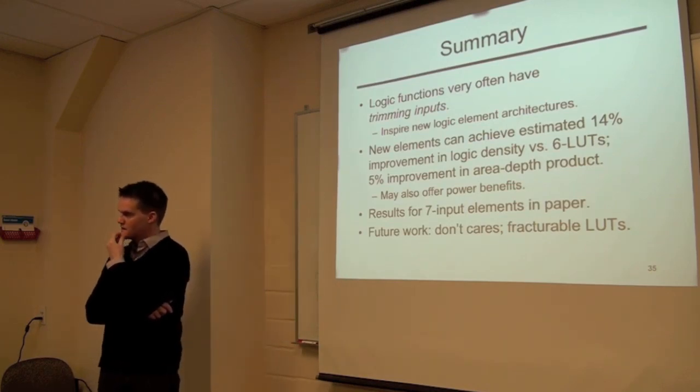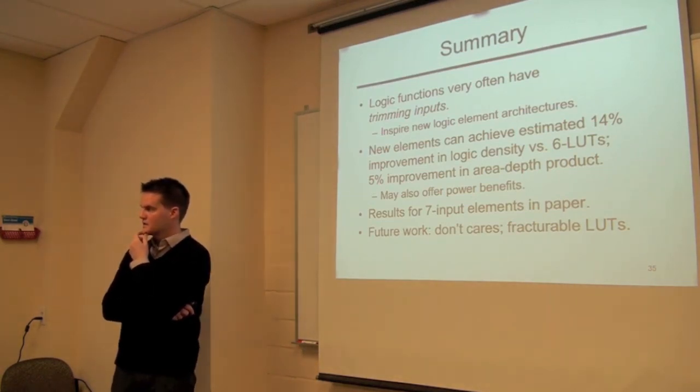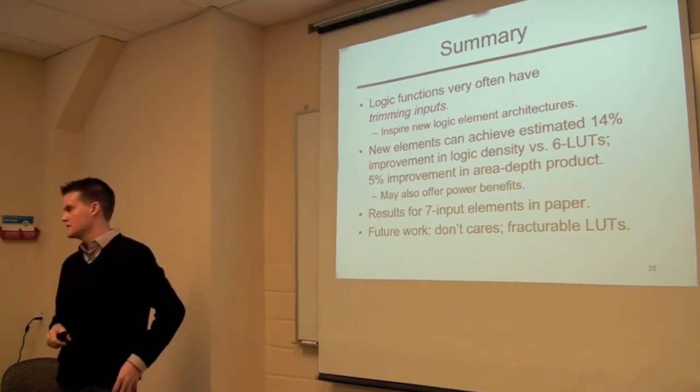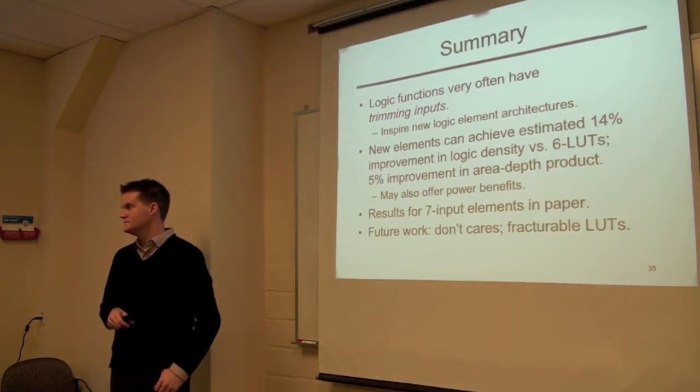It's probably two separate questions. Nowadays most clusters are depopulated, so really you should model that. Sure, but let's say you just ignore that, because that's arguably a separate question. You need a different delay for every LUT input. I didn't participate in the 5.0 upgrades, but the older version of VPR could do that in the timing graph, just not in the architecture description. Once you upgrade that timing, you at least get the LUT impact. You would probably still have a somewhat optimistic answer, because you're modeling a little more routing flexibility than people commercially build nowadays. But you can just say it is what it is, you model this, and you put that answer.